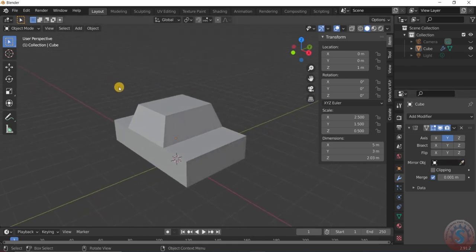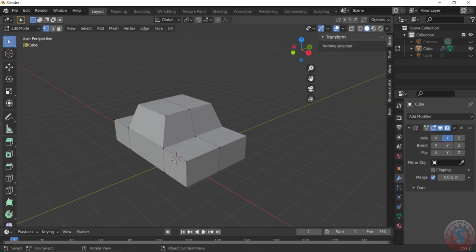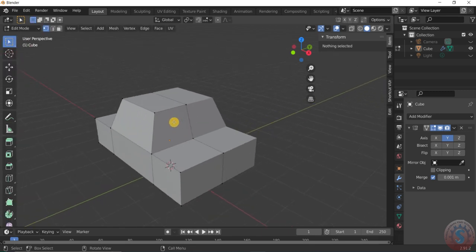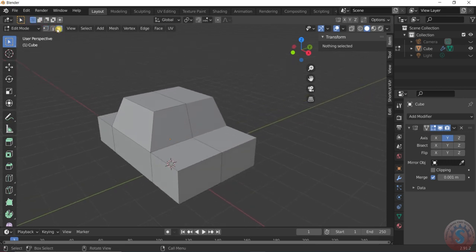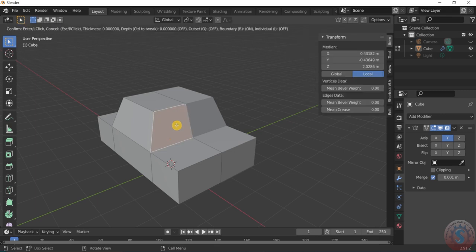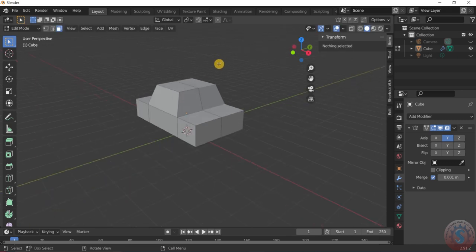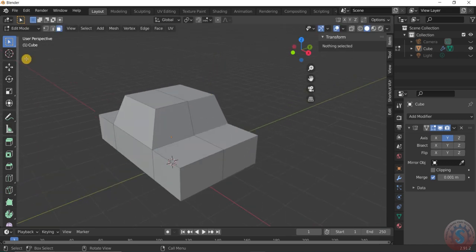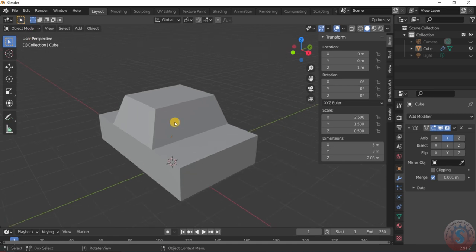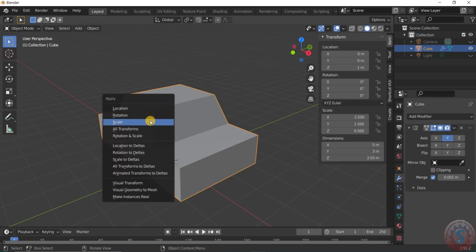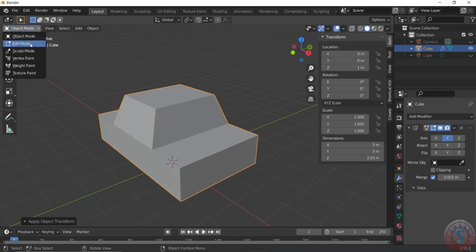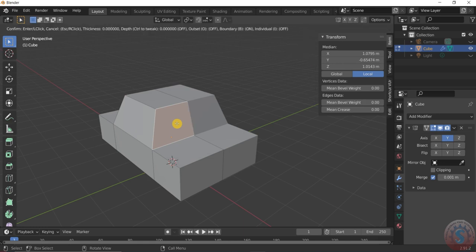Then I want to create the windows for the low poly. I go to the edit mode again and select the faces. By selecting the face and pressing the insert key I, you can give this, but all of the edges are not coming exactly right. In the object mode, press Ctrl A, select the cube using Ctrl A, scale this, and go into the edit mode again, select the face and press I. You can see.